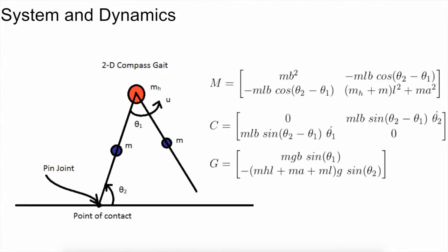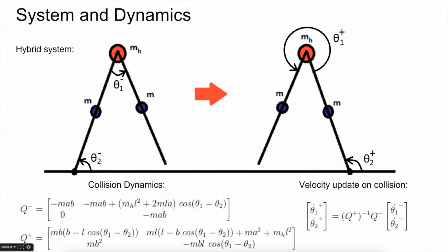The general dynamics for the compass gait and for the kneed compass gait are well understood and are shown here. An interesting feature of the compass gait and the kneed compass gait are some discrete impacts that happen during the course of walking. For example, when the compass gait switches the stance leg to the new stance leg, there is a loss of momentum that goes into the ground.